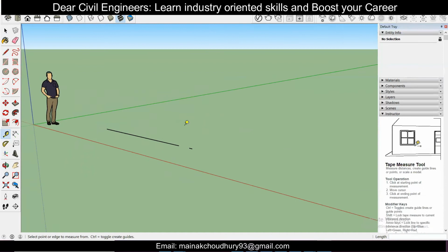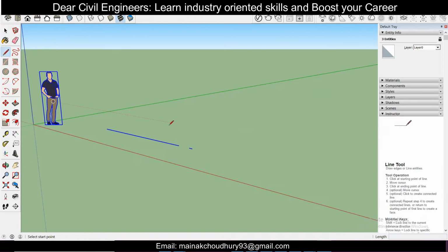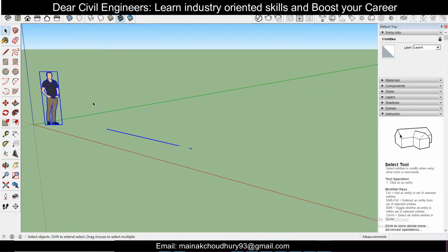And if you want to delete this, just press Ctrl plus A. It selects everything. If you want to deselect, you can click on the Select tool. Or if you want to bring up the Select tool, there is another option. Suppose I am in any other tool, if I just press space, then the Select tool will automatically come. So I'll select this and then click delete. I'll also press Ctrl plus Z. And if I want to deselect anything, suppose I've selected this, then shift plus click on it, and it is deselected. Then I'll click on delete.